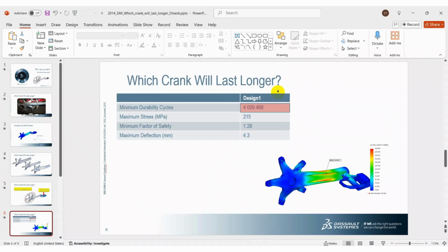Here you will be assigning the material and importing the material, and also we are going to mesh it, and we are applying an SN curve over the material, and the SN curve takes advantage of that and applies the conditions and gives us the result: how much life cycle it could withstand, and also the damage tolerance which we have given.